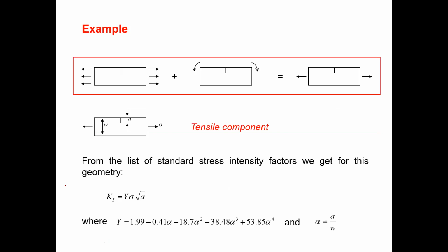For the tensile component, you need to find the proper graph, the proper figure, because this is a surface crack under tensile load. So you can find out the Y value. Normally they will provide in the annex, under the equation, the figure and the Y factor. So this is the Y factor.